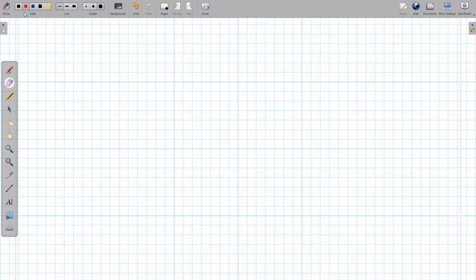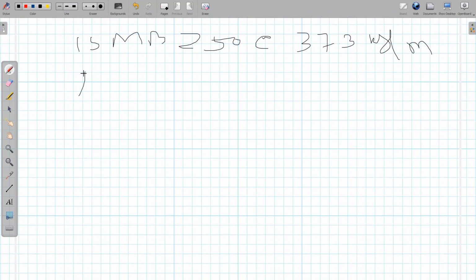How to redesign it? To do the redesign, now you have to choose another section from the steel table whose area must be more than whatever we have chosen, or its radius of gyration must be more than whatever we have chosen earlier. If you have the steel table, then try with this one, ISMB 250 at the rate of 37.3 kg per meter.